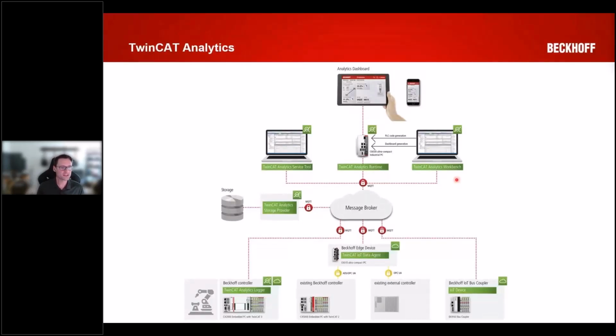That being said, you have access to those projects. So you can add logic onto them. You could modify the HMI and add your own custom graphics. Now, that's not always a great workflow, because again, we're dealing with code generation here. Typically you want to work within this engineering environment. That way, when you generate a new version, it's not overwriting a bunch of changes that you custom made to this runtime. But it is possible because they're just PLC and HMI projects.